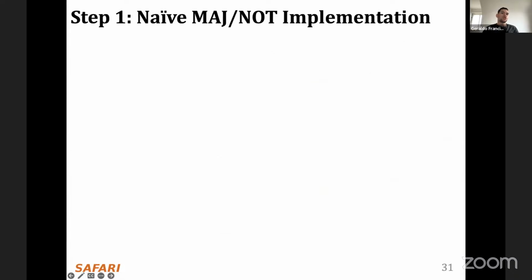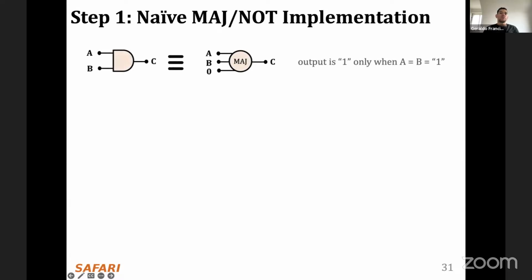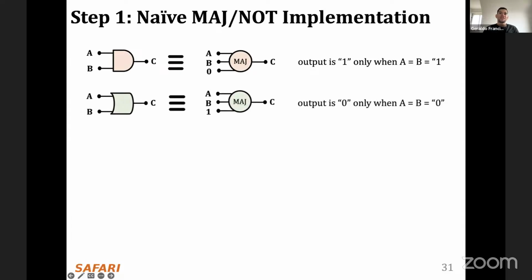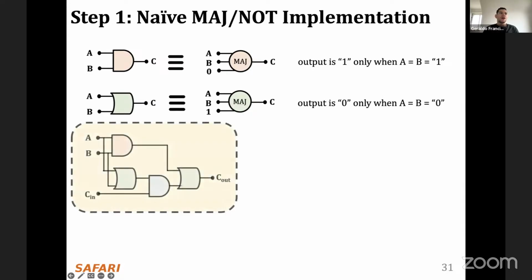As shown earlier, it's quite trivial to convert Boolean equations to the equivalent majority equation, as each two-input AND is implemented using a three-input majority primitive, where one of the inputs is tied to logic 0, and the OR primitive is implemented using a three-input majority primitive, where one of the inputs is tied to logic 1.